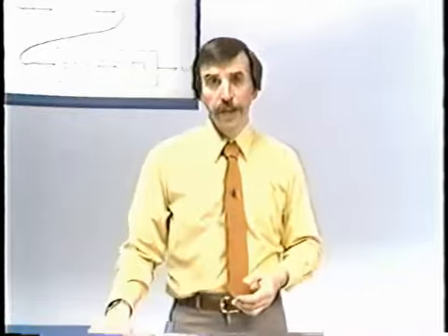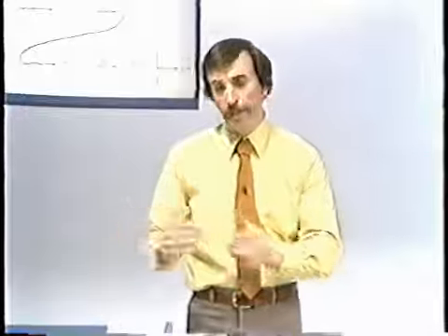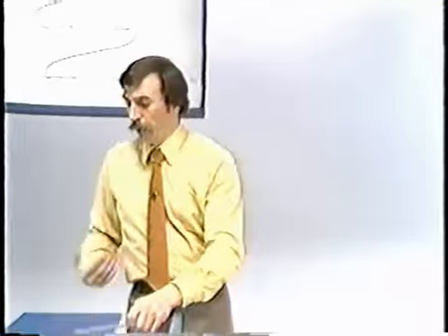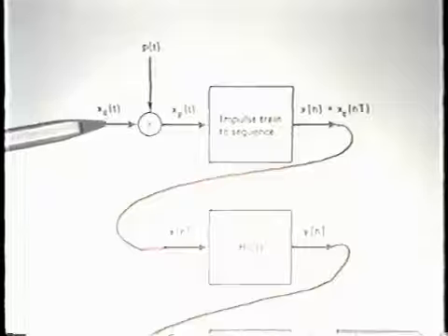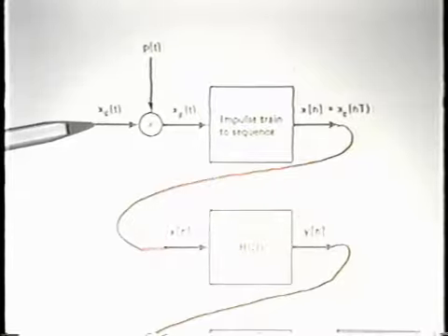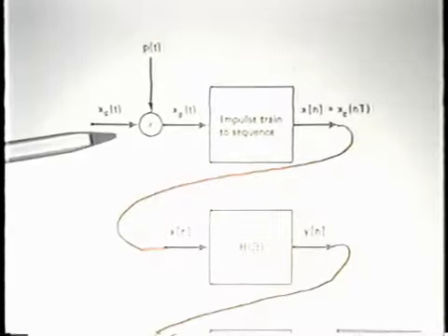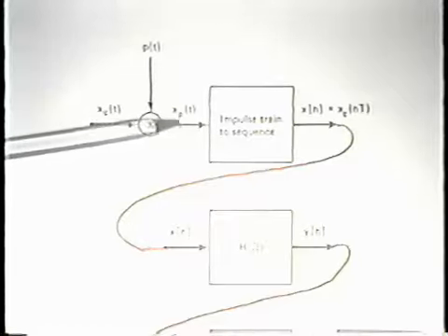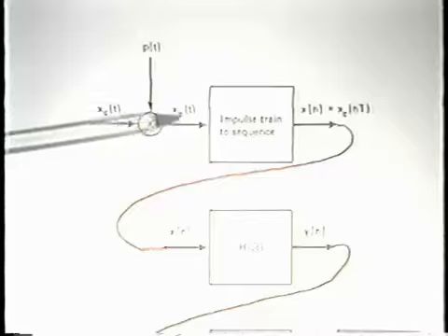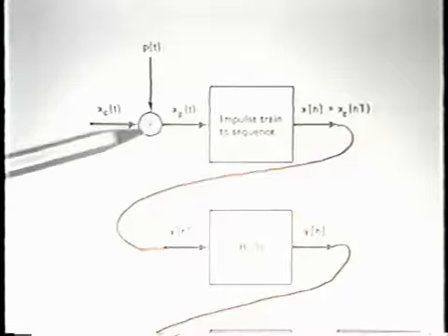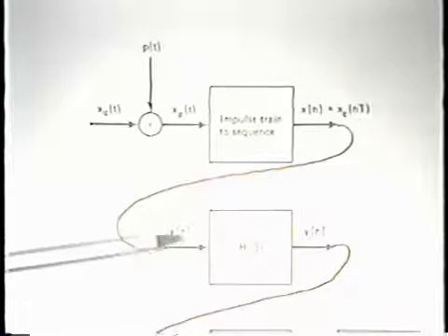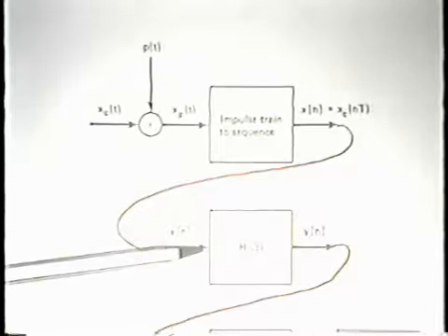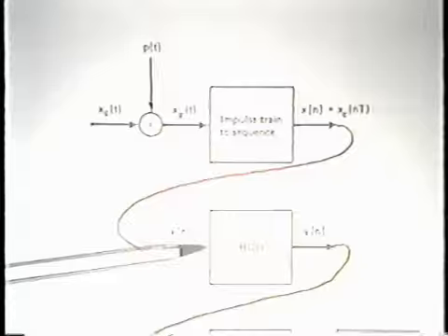A consequence of that, then, is that as we go through the processing and we demonstrate the frequency response of the system, what we'll see in the output is no aliasing when the input is below 10 kilohertz. As the input sweeps past 10 kilohertz, when we let it, which we will eventually in the demonstration, then in fact that frequency, as it finally shows up here, will begin to be aliased down into a lower frequency.